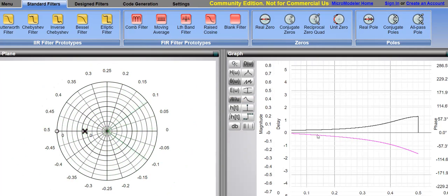What does it mean by this group delay? For the low frequency, the delay is low. For the high frequency, the delay is high, and classically that's supposed to be. Now the question is, we need to design an all pass filter so that we can counterbalance this. So now we can introduce an all pass filter there.